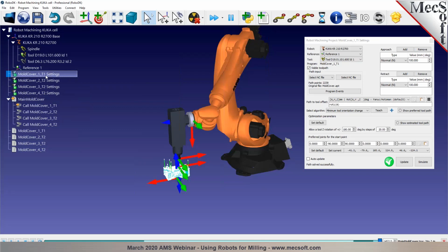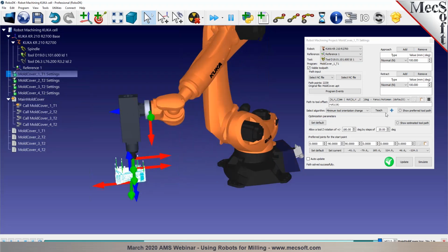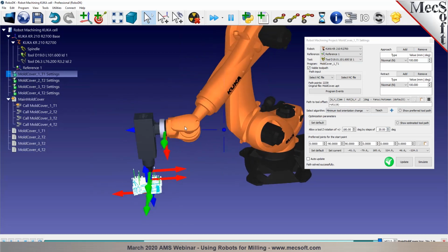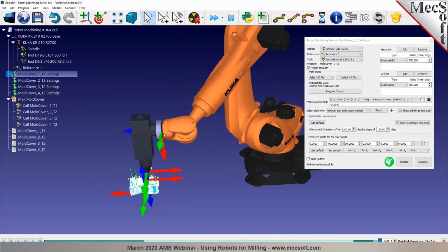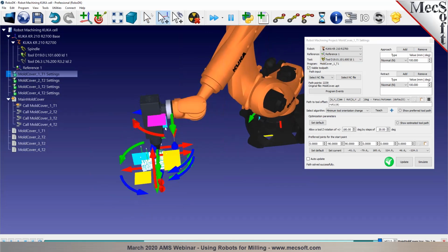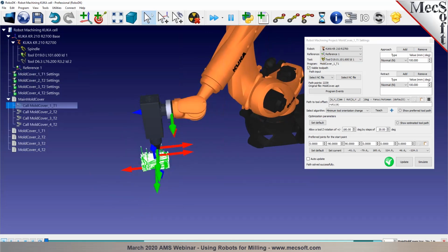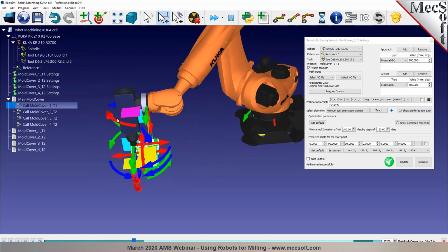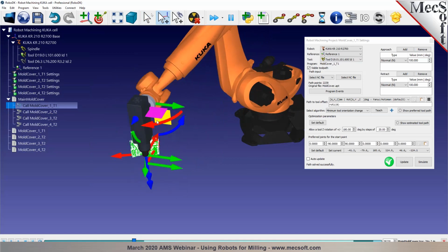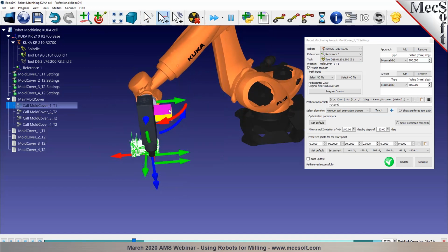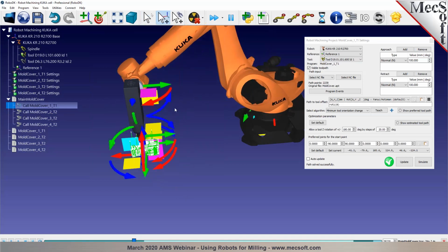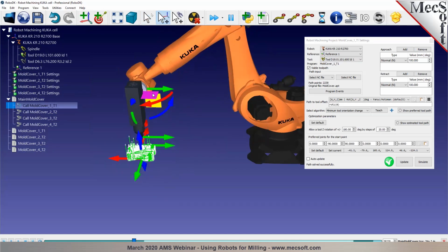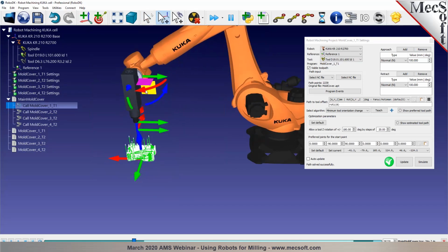So to go into more detail here, this will help you define the additional degree of freedom you have with a 6-axis robot. Right now, a machining operation has a certain orientation for the tool. You may want to change this orientation and do the machining operation using a different orientation. So right now I'm using the Alt key to move the robot and change the orientation.